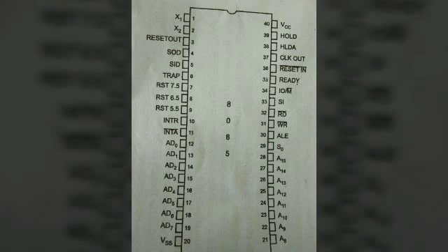These 16 address lines are split into two segments, that is AD0 to AD7 and A8 to A15. The 8 address lines A8 to A15 are unidirectional and serve as the higher order address bus. AD0 to AD7 are bidirectional. These lines serve as both address and data bus.